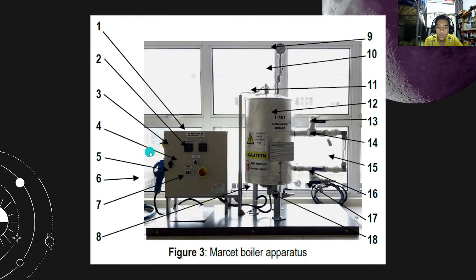First we will switch off the water heater and leave the vessel to cool down until it reaches room temperature. Next we will switch off the main supply after the boiler has reached room temperature. Next is to return the water for the next experiment.